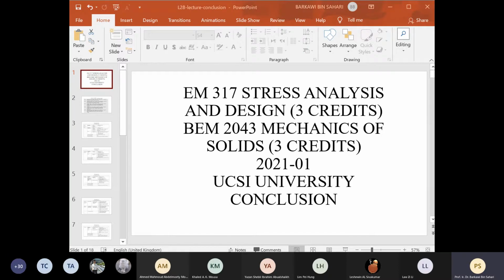And another difference might be if we are reading graphs, the value of stress concentration factors. There are some reading as low as 1.2 and some as high as 1.5, whereas the value for that is actually 1.3 or 1.35. So that caused quite a lot of problems in terms of checking the answers.